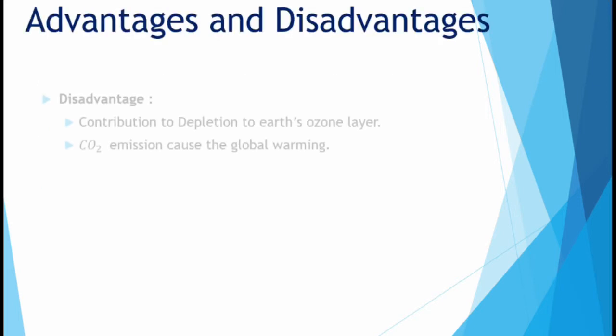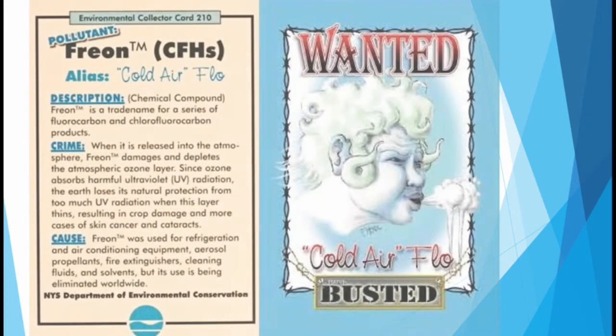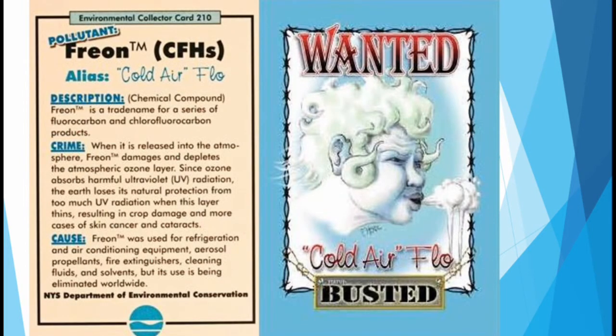Advantages and disadvantages of the VCR system. Disadvantages: first, constant contribution to depletion of Earth's ozone layer. Carbon dioxide emission causes global warming. Advantages: relatively inexpensive, very mature technology, can directly be driven by mechanical systems.